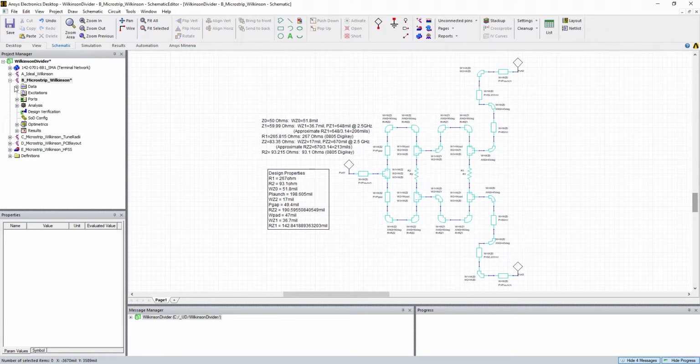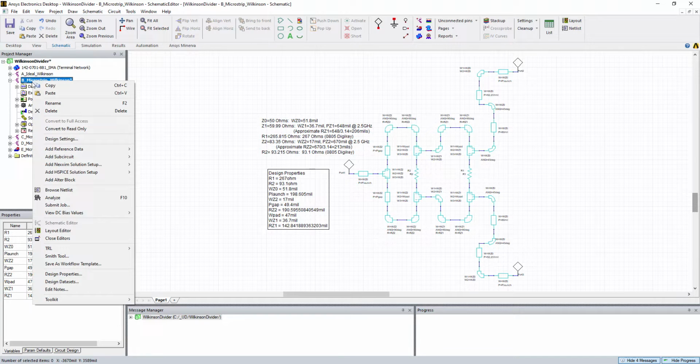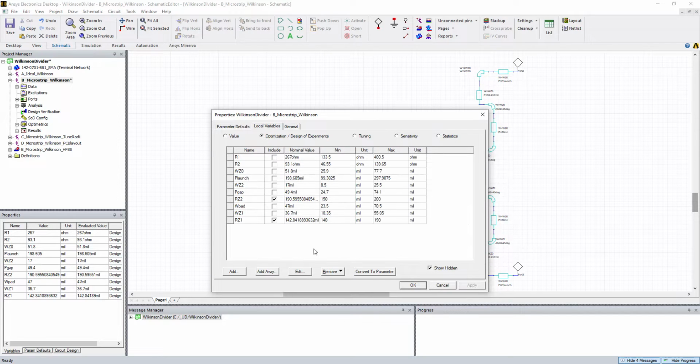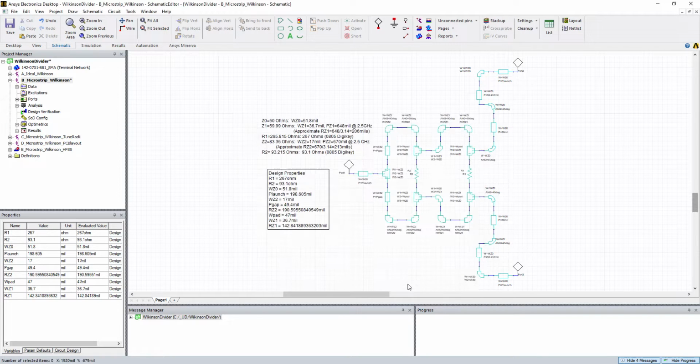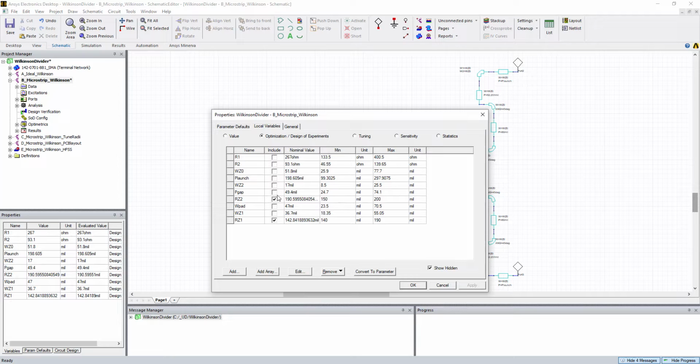So yeah, and just to optimize, I mentioned optimization. You right click on your circuit, you hit design properties, you'll notice that we're only going to optimize the radius for Z2 and the radius for Z1, those radial bends, and you'll put your initial values that you guesstimate here and give it a range, and you're going to optimize each one of them. So you selected two variables, right? Just so we're clear, R sub Z2 and R sub Z1, we're going to optimize both of them.